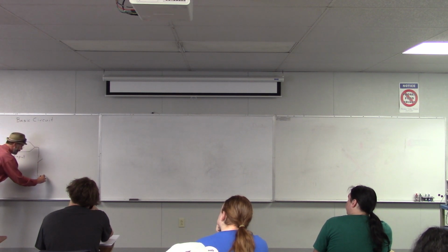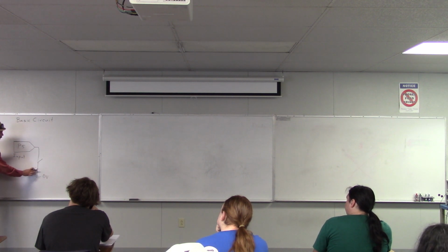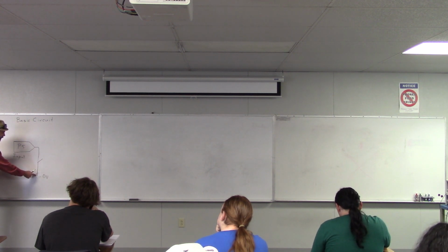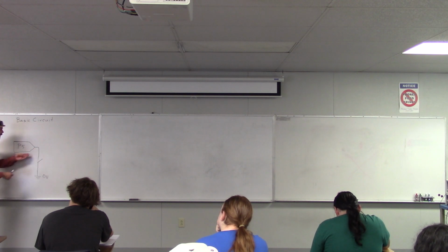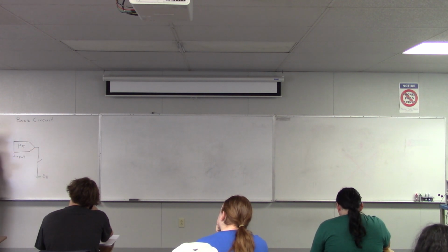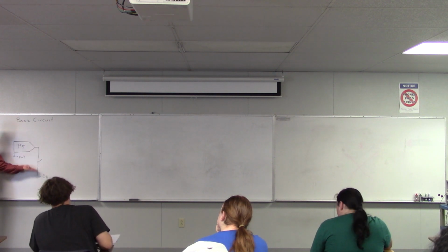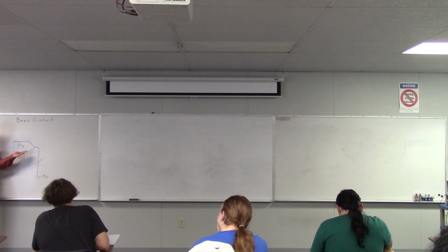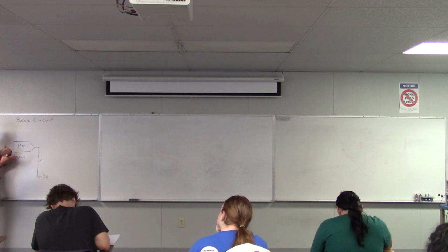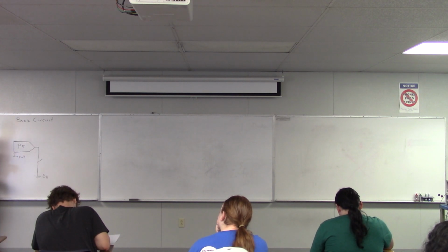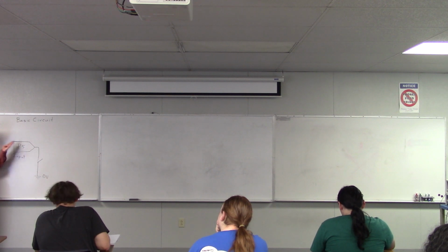Now ground is at 0 volts, and the voltage is constant along any wire. So when the switch is closed, it's making essentially a straight wire from ground to this pin. What voltage would we have at that pin? Well, not 5 volts. It's connected directly to ground. Oh, yeah. 0 volts, exactly. So when the switch is closed, we get 0 volts there. So that sounds good. We're creating a low voltage. But there's a problem with this circuit.